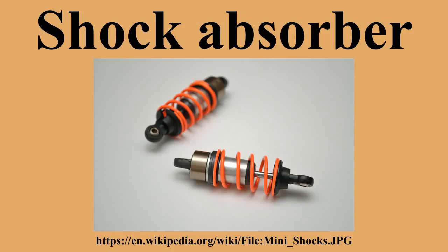Compression of a gas, for example pneumatic shock absorbers, which can act like springs as the air pressure is building to resist the force on it. Enclosed gas is compressible, so equipment is less subject to shock damage. This concept was first applied in series production on Citroën cars in 1954. Today, many shock absorbers are pressurized with compressed nitrogen, to reduce the tendency for the oil to cavitate under heavy use. This causes foaming, which temporarily reduces the damping ability of the unit.